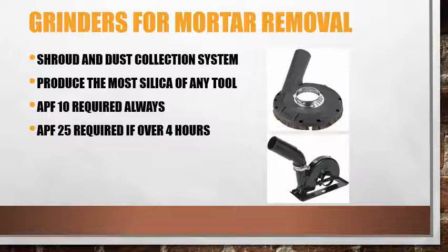A very important tool to mention is grinders for mortar removal. The shroud and dust collection system can be attached to the grinder when removing mortar. The grinder being used for mortar removal produces the most silica dust of any tool. Grinding mortar, which has the most silica in it, more than stone or block or brick, and because of this, you need to be wearing an APF10 always.